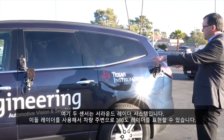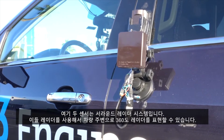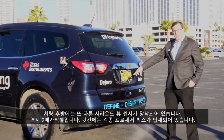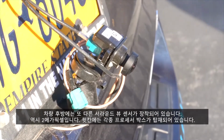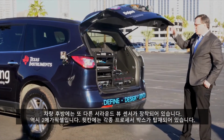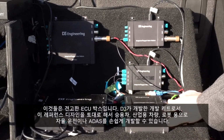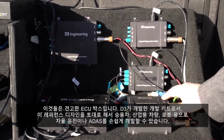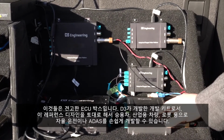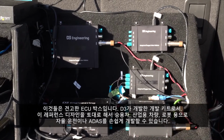Okay, these 2 sensors here are part of the surround radar system. Again, they feed in and give a 360-degree bubble of radar around the car. On the back of the car is the last of the surround view sensors, again a 2 megapixel. And then inside the back are all the different processor boxes. These are rugged ECU boxes, development kits, available from D3, reference designs as starting points for either automotive, industrial vehicle, or robotics, anything in the autonomous or ADAS space.